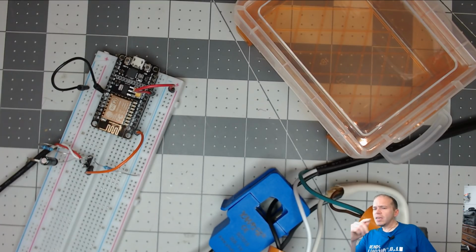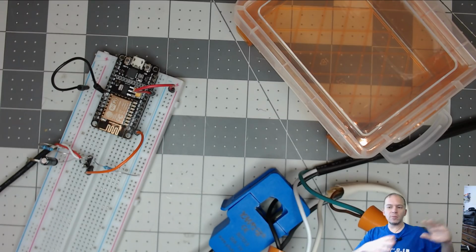So Stuart, yeah, you can use the 200 amp. It's all down to the size clamp. And correct me if I'm wrong, I think that's 200 amps on each leg, I believe. It's not combined on each phase. You have to look around, because if you do get up to 200 amp, you won't want to blow out the spec on that. Say if you put 100 amp on there, you can get the 200 amp clamps and put those around. I know some people had some larger wires and they had to find some bigger clamps.